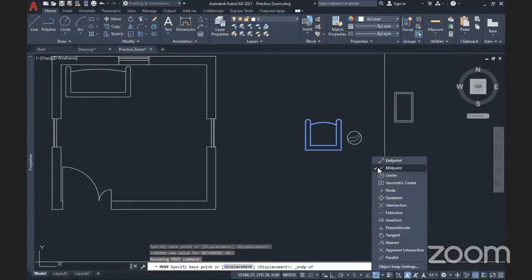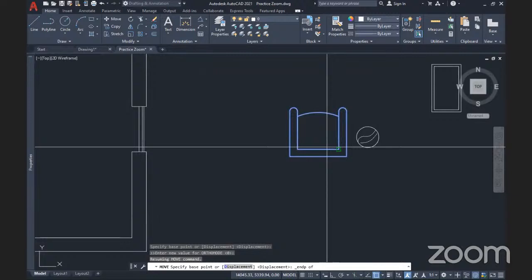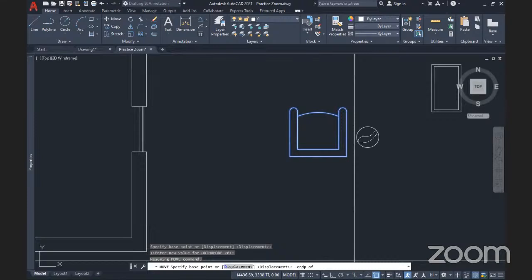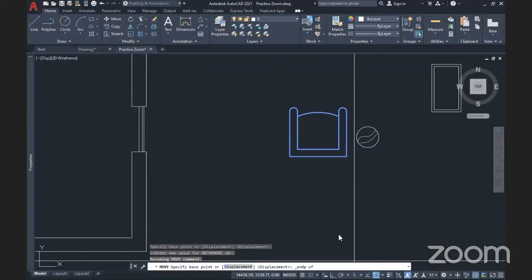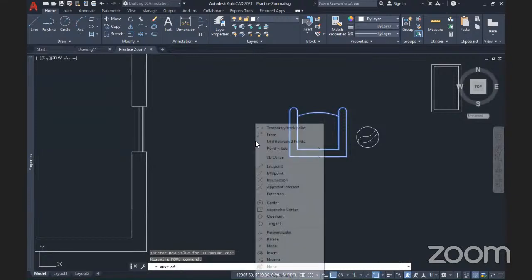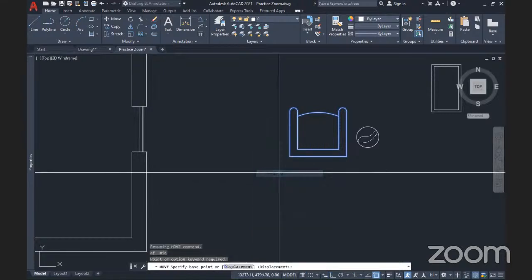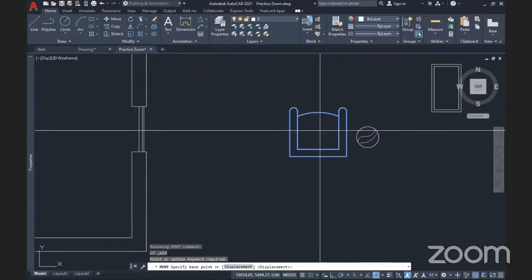This midpoint, as you can see, or you must have guessed, helps you snap to midpoints on objects. Let's say this is the endpoint, it's been selected. Now look here, you see a midpoint. Let me select the midpoint option. I'll Shift right click also. Before I selected endpoint, so it restricted the whole movement to endpoint snapping. Now I'm coming to select midpoint. Now it will restrict all my snap to midpoints, like so.